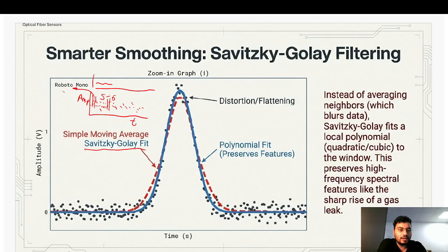The first point is dropped and the next one is added. Suppose previously points 1 to 10 were used; the first point is removed and we start from 2 to 11. If you do it like that, it averages out and you get lesser noise.